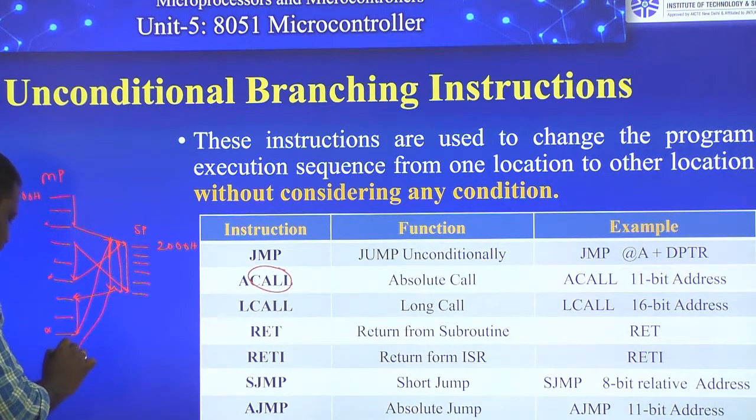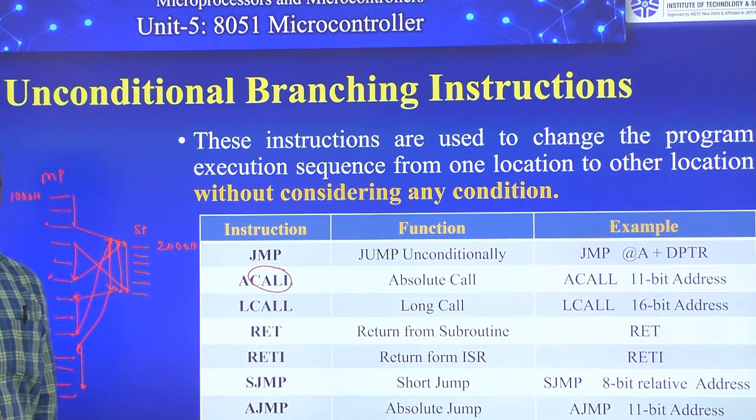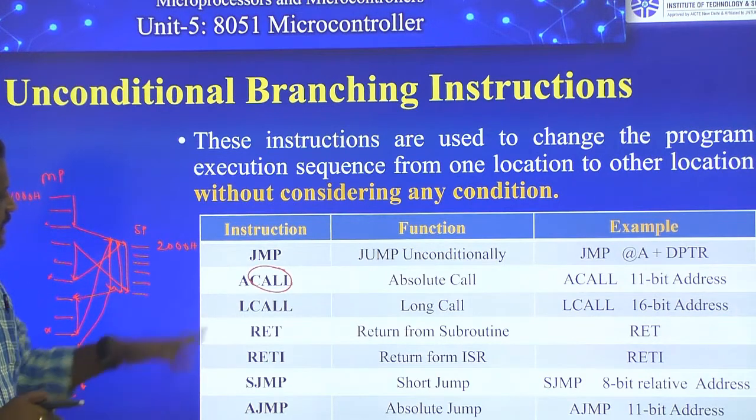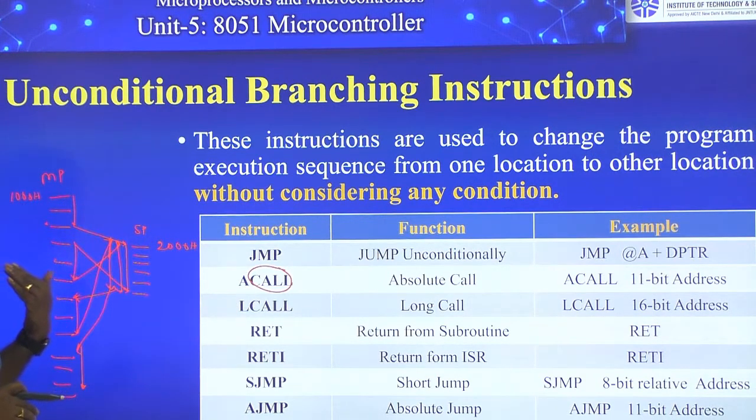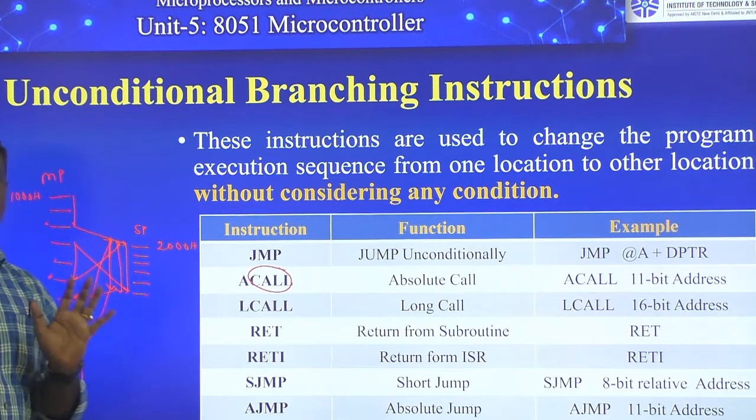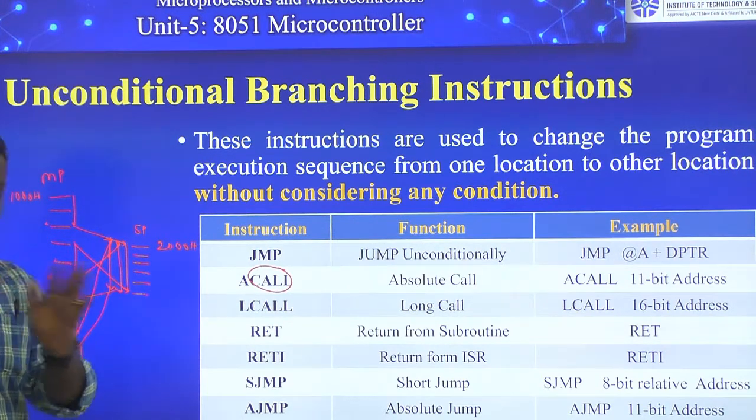After finishing that, again I come to the main program, and it continues the execution of the rest of the instructions. So basically the CALL instruction is used to call a subprogram into the main program, but originally our execution sequence changes from the main program to the subprogram. You remember that.